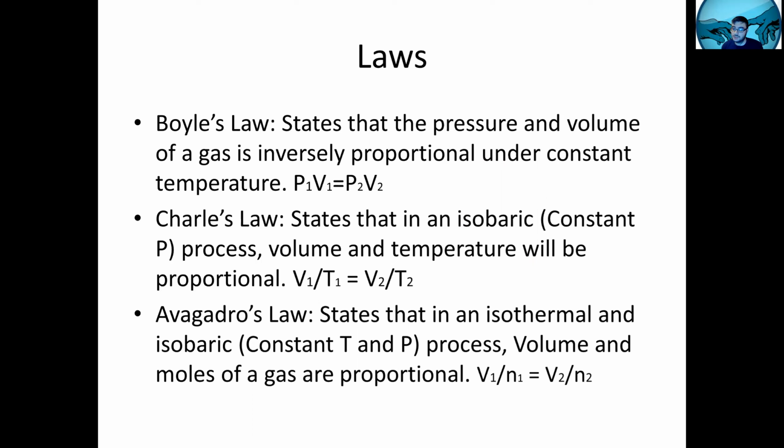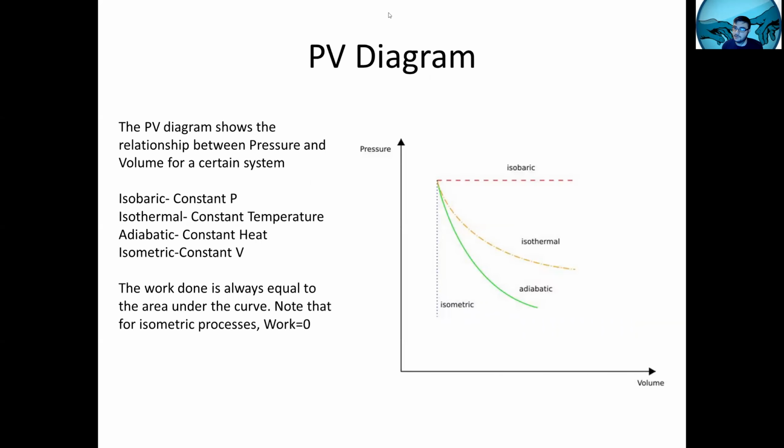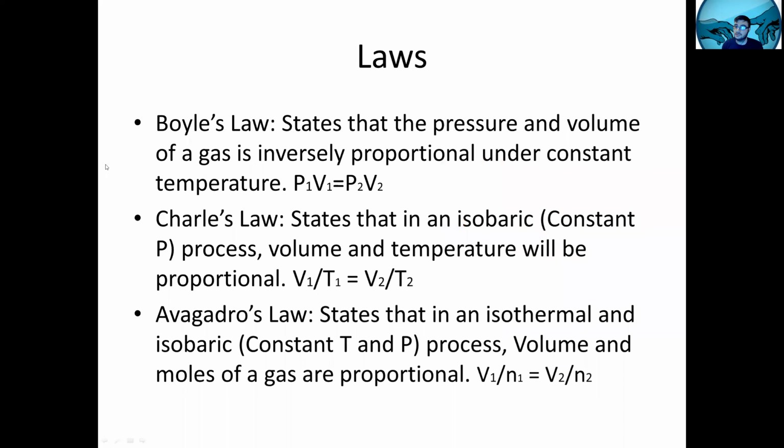And actually, if you want to see this, you can see here that constant temperature, which is isothermal, this one, as the volume goes up, which is to this side, the pressure goes down, right? As the pressure goes up right here, the volume goes down, inversely proportional. So that is a physical way to see Boyle's law.